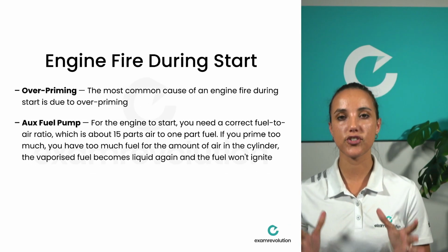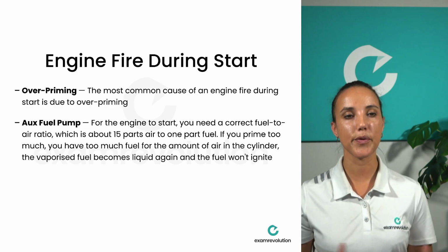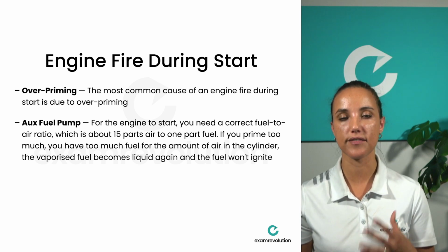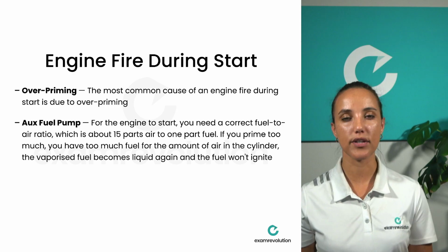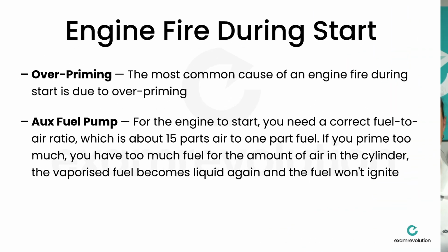So for the engine to start, you need the correct fuel-air ratio, which is 15 parts air and 1 part fuel. If you prime too much, you have too much fuel for the amount of air in the cylinder, and the vaporized fuel becomes liquid again, and the fuel won't ignite.